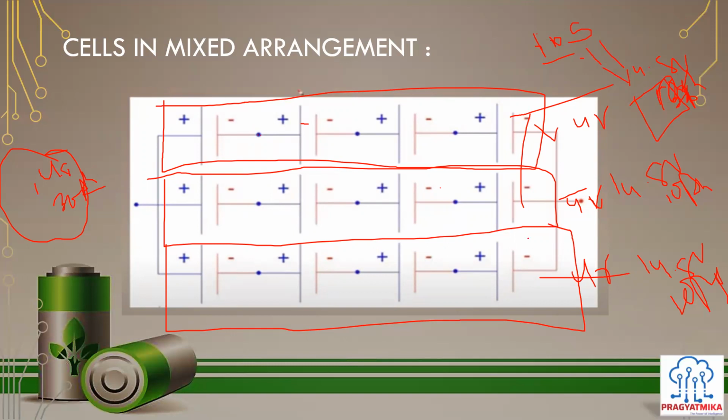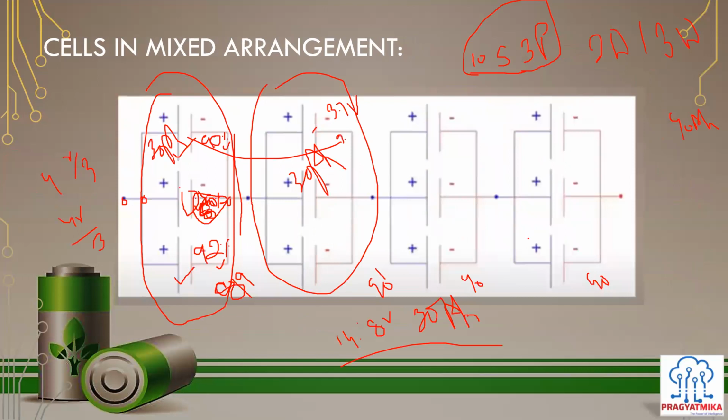Also, in this master slave, at the slave level, it is monitoring the individual cells. If we are doing a series-oriented mixed arrangement, then the slaves will be monitoring at the cell level. Also, it is not that master slave is not used in a parallel arrangement.